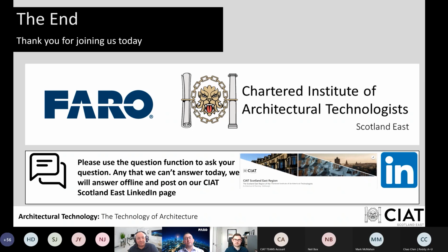If you're going to be doing stuff where it's going to be covering over information and you're not going to get overlap, then that's when you would start using your target systems and your checkerboards, just to make sure that there's enough information there. But it's far, far easier to start scanning now just with automatic registration, as long as you've got the coverage in there. Yeah, superb.